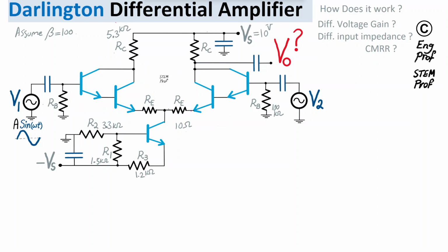of the circuit. The circuit has a mirror symmetry with respect to the center, and then we have, aside from transistors T1, T2, T3, T4, a BJT (bipolar junction transistor) T5 here that serves as the current source at the bottom of the circuit that provides a DC current to feed the two left and right mirror symmetric branches, so they have the same DC current value.